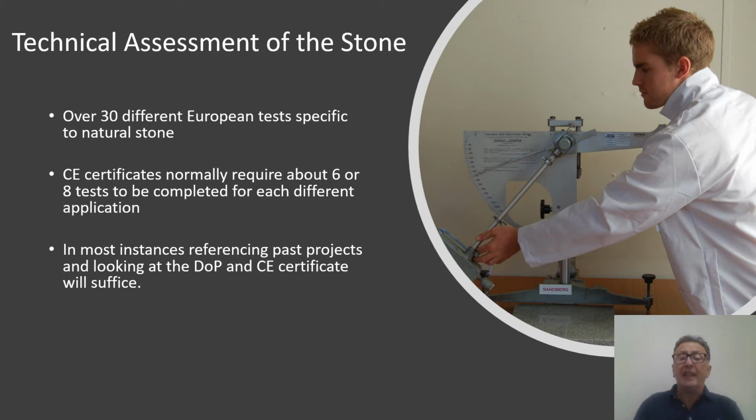However, don't forget that in certain applications that stone may have to be resistant to de-icing salts, and it may not always be the case that a test appropriate for testing that stone's performance with regards to the impact of de-icing salts has been presented. And so that would be one test that you'd be looking to reproduce prior to confirming the selection of that material.